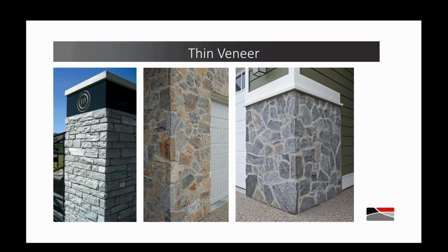The corner is critical, as it is with any thin veneer in masonry, to create that illusion of full bed material that you're trying to achieve. Without a 90-degree return, it really does just look like a flat piece of stone bonded to a wall. But with the use of the corners at 90 degrees, it creates that full bed illusion that we are all looking for.